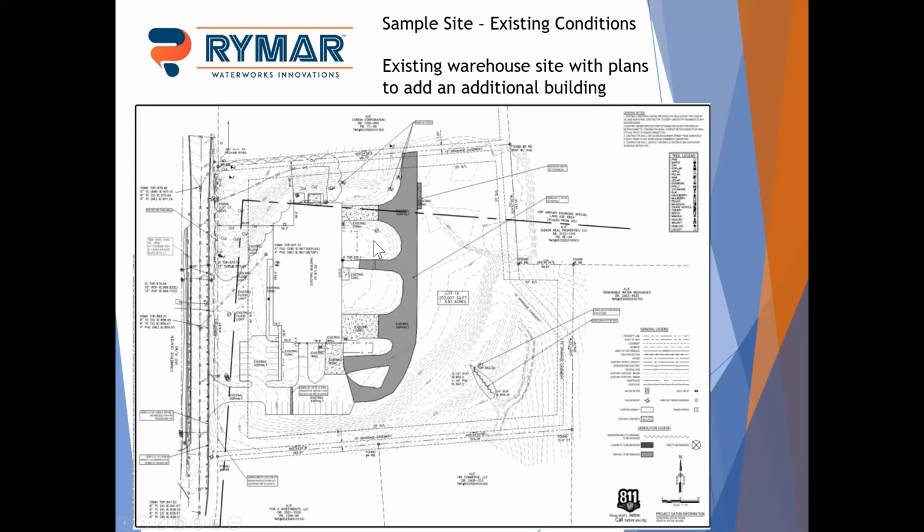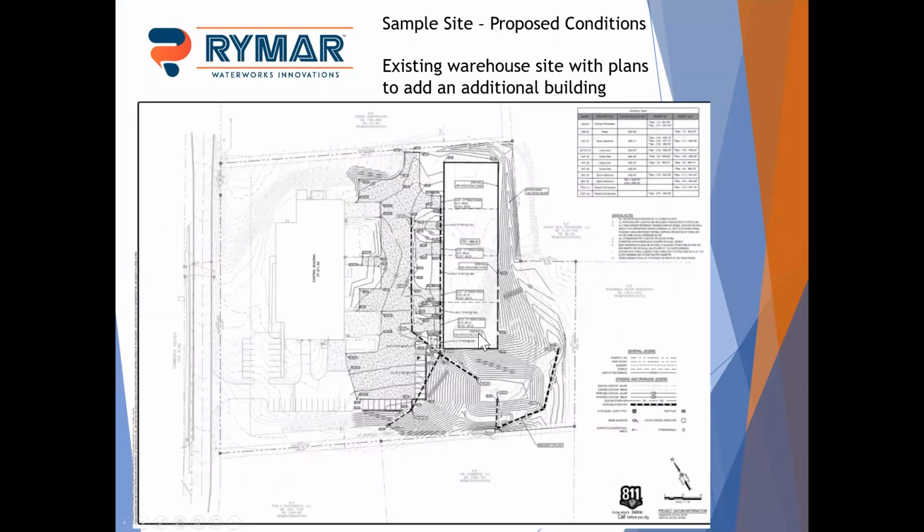So this is a site that we did in Greenville County, South Carolina. It was an existing facility, had a warehouse and some truck areas, and they wanted to add an additional warehouse here on the backside. So they had enough area to try to do that. So here's the proposed design, a new building, new trucking. Here's the new basin that some of the existing site water as well as all the new site waters go into, and this basin was being used as a sediment basin during construction.